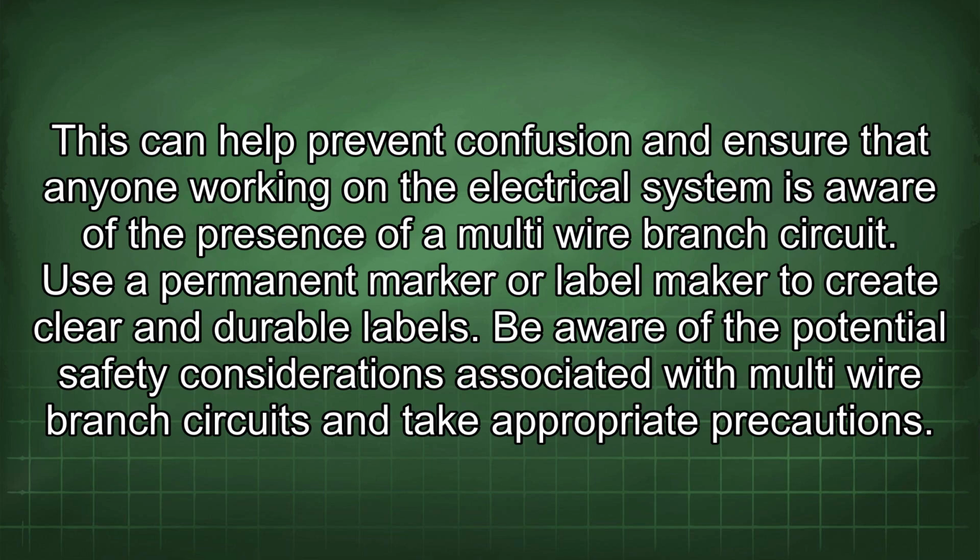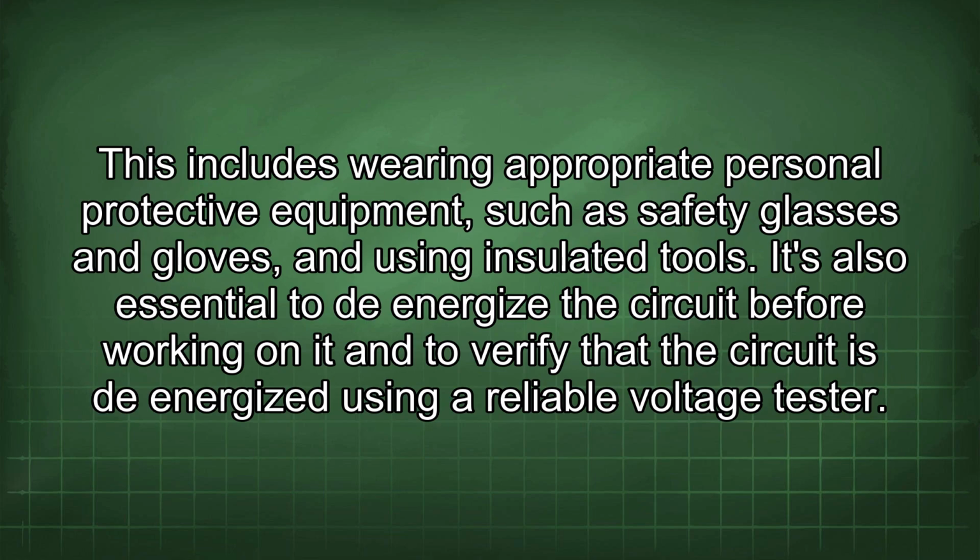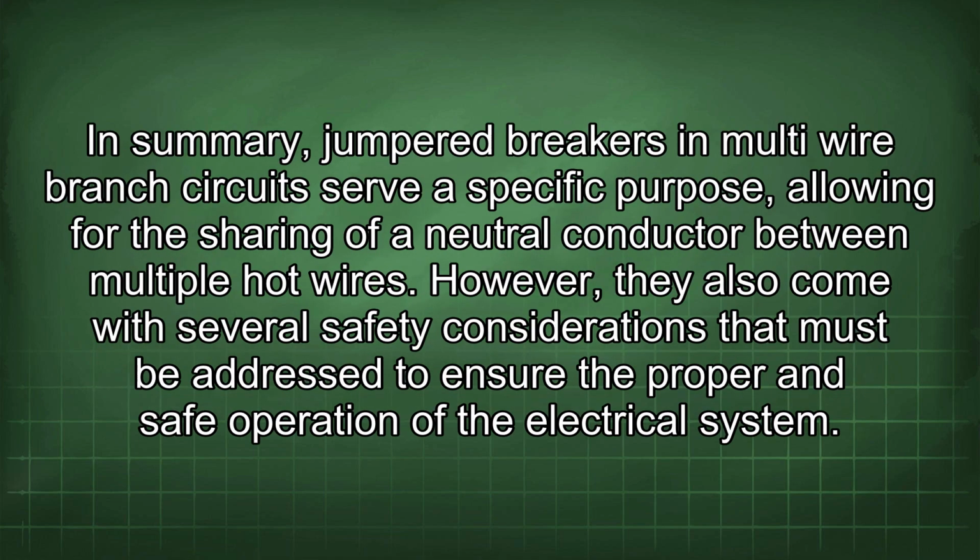Be aware of the potential safety considerations associated with multi-wire branch circuits and take appropriate precautions. This includes wearing appropriate personal protective equipment, such as safety glasses and gloves, and using insulated tools. It's also essential to de-energize the circuit before working on it and to verify that the circuit is de-energized using a reliable voltage tester.